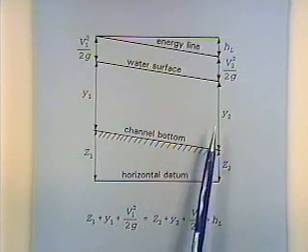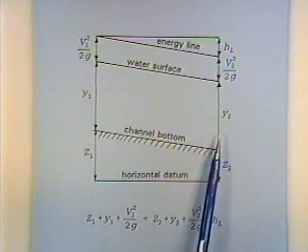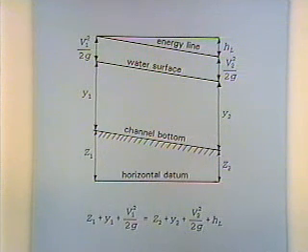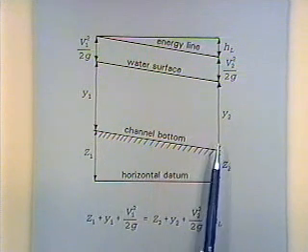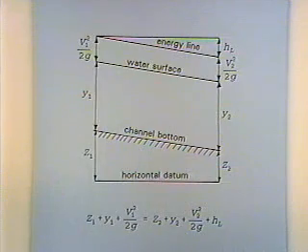Now gradually varied flow means the depth changes along the length of the channel. And so what we'll be doing is having a known depth someplace, computing the depth all along the channel. There's two ways of doing that. Conceptually, we're working with the energy equation, using Manning's equation to estimate head losses either way, but the computational details vary between the direct step method and the standard step method.